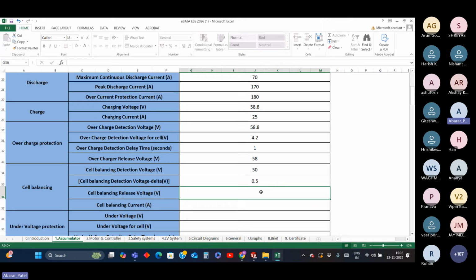Either it can take charge from one cell and push it into another, this is active balancing, and the other one is where it drains the voltage and converts the energy into heat, in passive balancing. When it will balance depends on this delta voltage. If it exceeds a certain value, your balancing process will be started by your BMS within your battery pack.